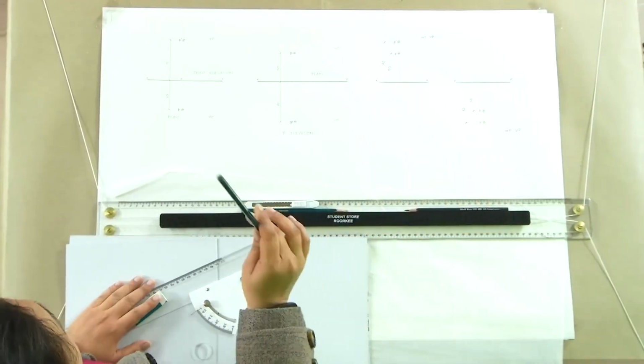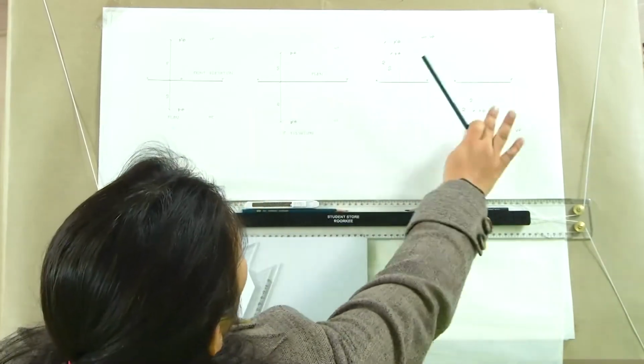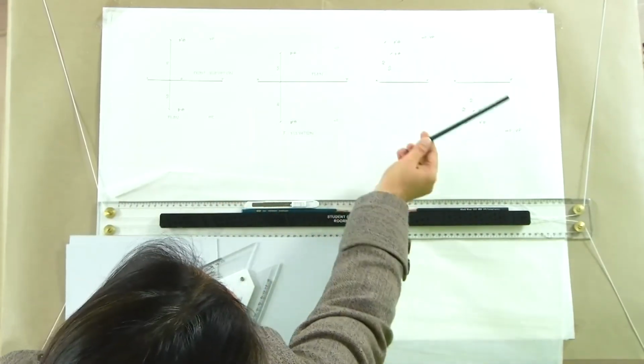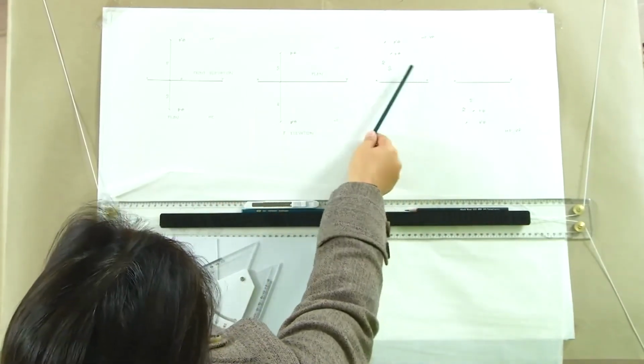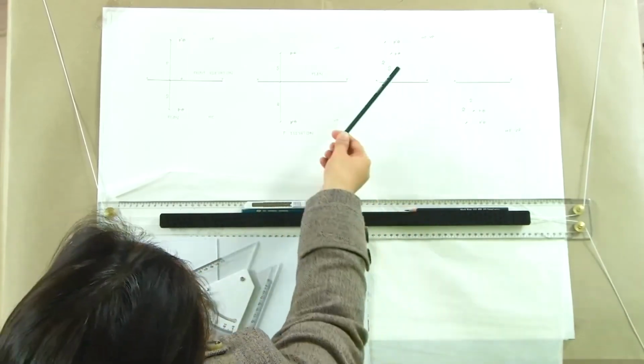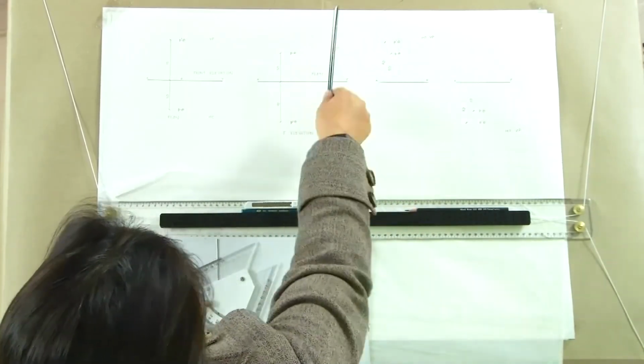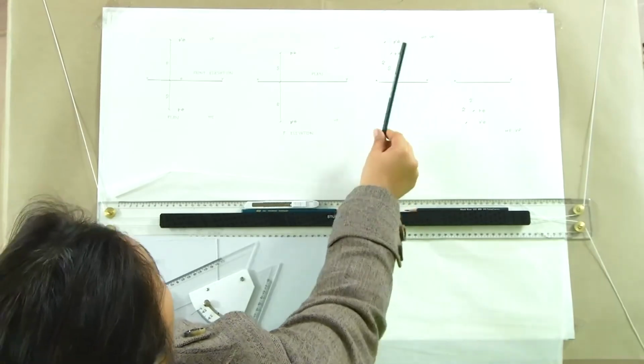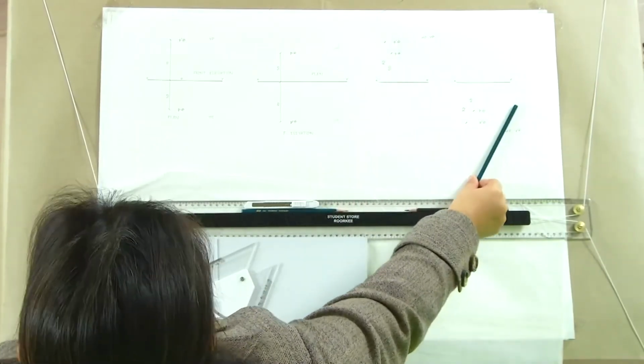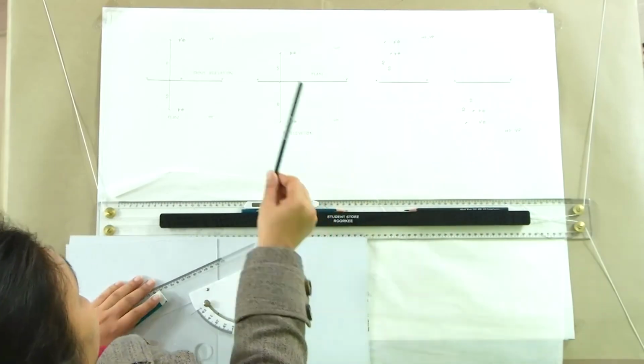Now, one thing which becomes very clear from this drawing is that the second quadrant and fourth quadrant are not very convenient to read, because the projections will intersect and overlap. That is why we do not use second and fourth quadrant drawings. We preferably go for the first quadrant or the third quadrant. In India, as I said earlier, we use the first quadrant, while in several countries including the United States of America, they follow the third quadrant.